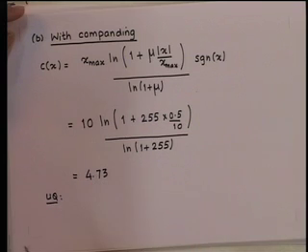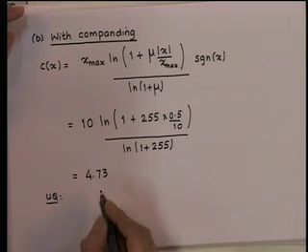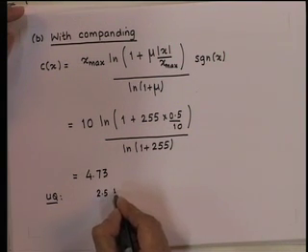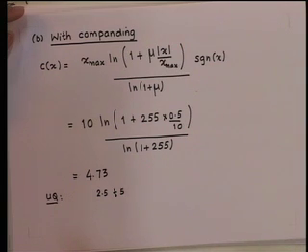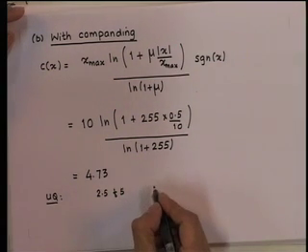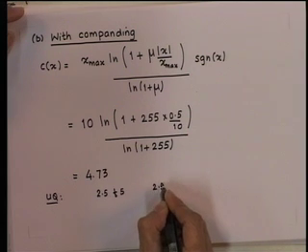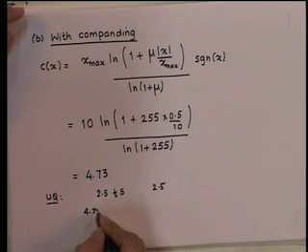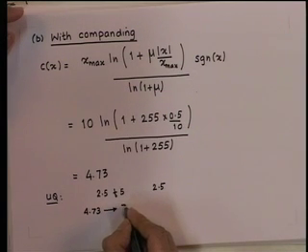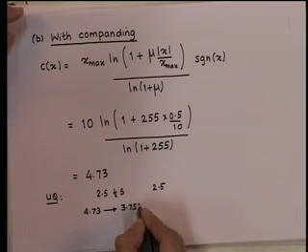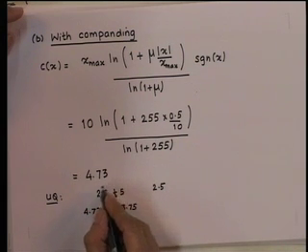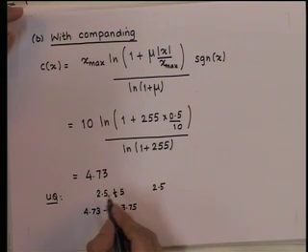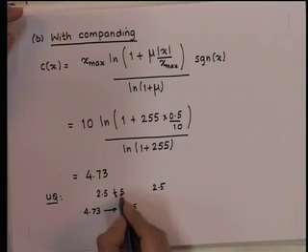Now, 4.73 lies between 2.5 and 5, and we know that the quantization step size is 2.5. Therefore, 4.73 will get quantized to 3.75, which is the reconstruction level for the interval between 2.5 and 5, that is the average of these two values.